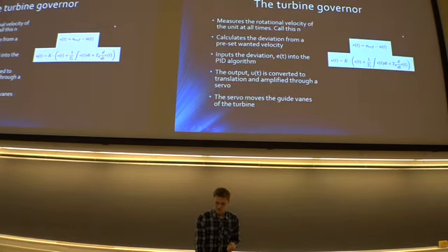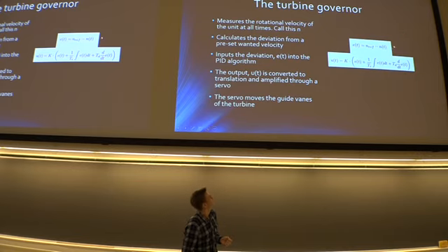So the governor algorithm looks like this. It's not as complicated as it looks. So if you remember the figure from earlier slides, then N would be the RPMs of the power units, and the reference is just 50 Hertz, or the rotation based on the number of pole pairs on the generator, and you find the reference.